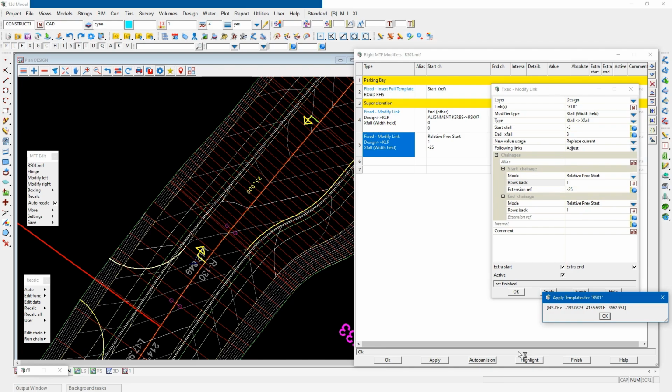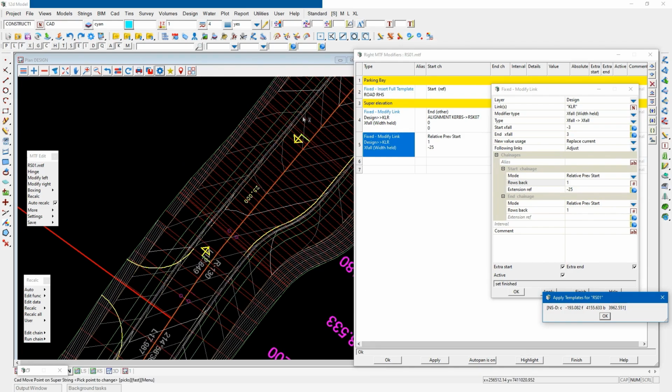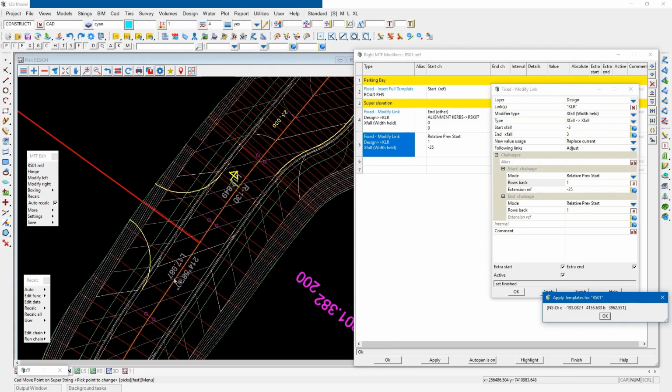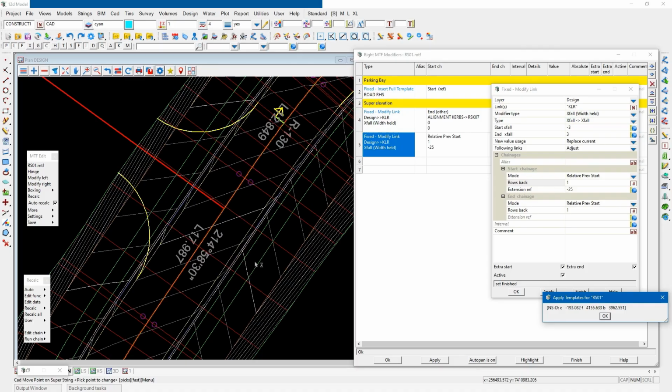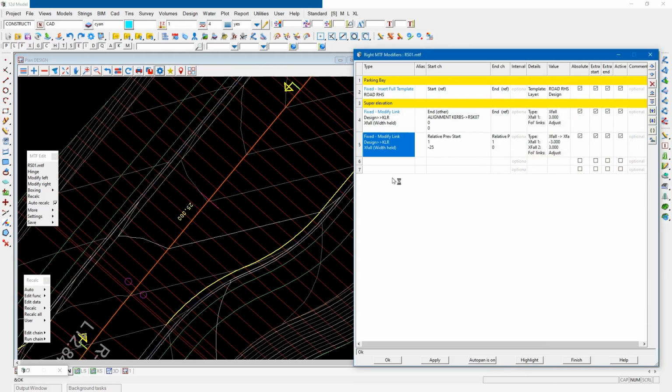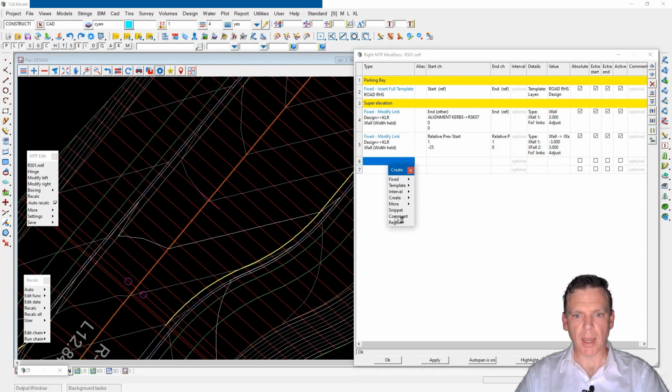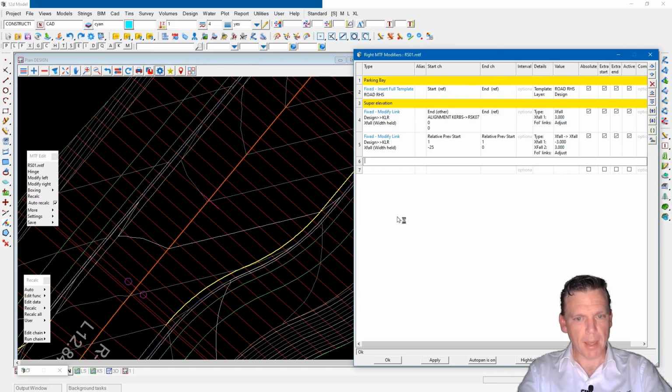And you can see that the pavement transitioning up from a -3, it's flat in the middle here, then it's transitioned across to the +3 over this side. So that's all working pretty nicely for me. Now I might just want to remove some links through the intersection itself. So I'm just going to come in here and put in another command, remove links